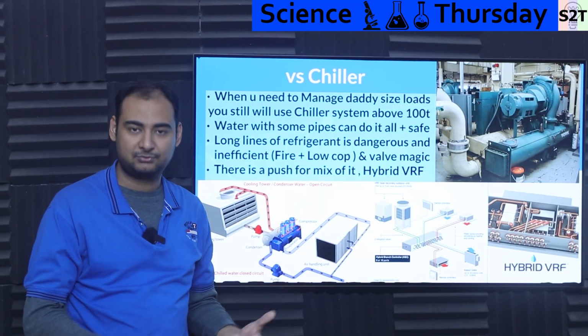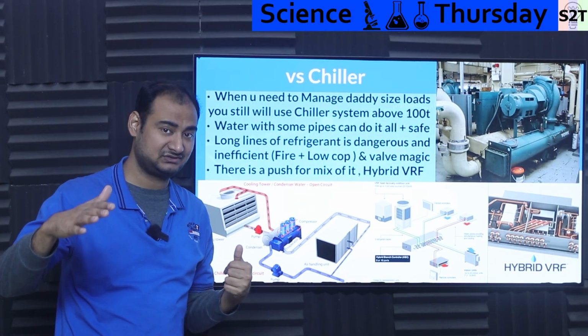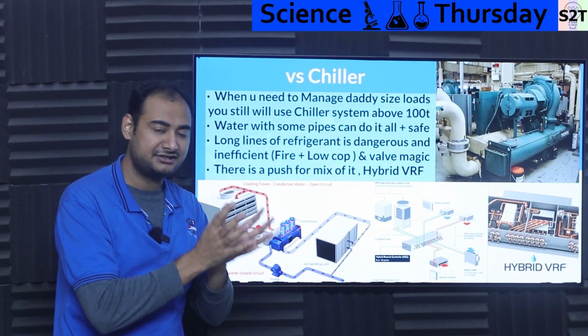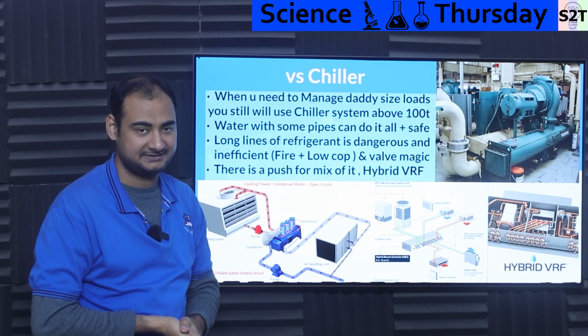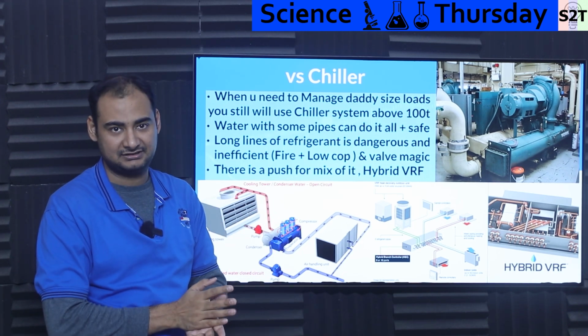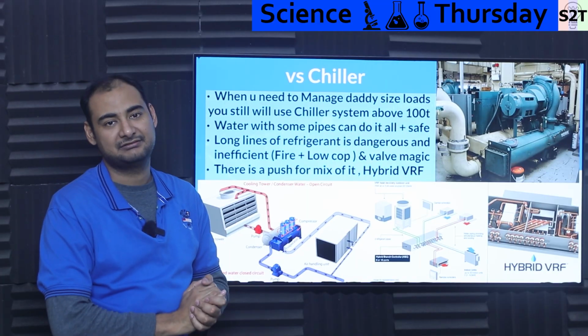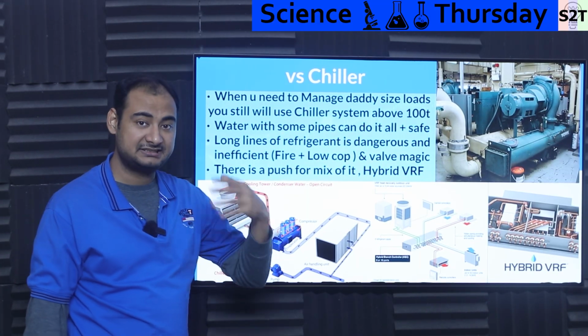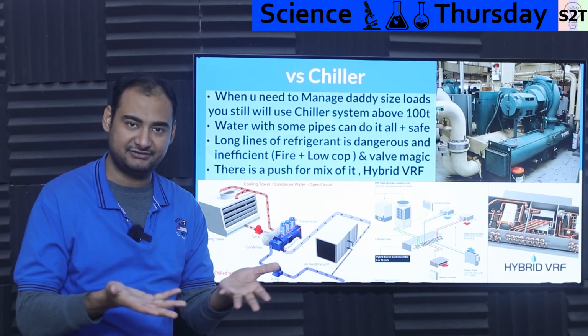It's like, hey, we have propane or ammonia. Ammonia is the best. The best refrigerant is ammonia. But again, it's toxic. But if it's concentrated in one place, you can have safeguards there. Like, hey, design this place to have a positive airflow. Design this place to have a fire resistance, so to say. So it can be done. So that itself gives you far more choice when it comes to your refrigerant.